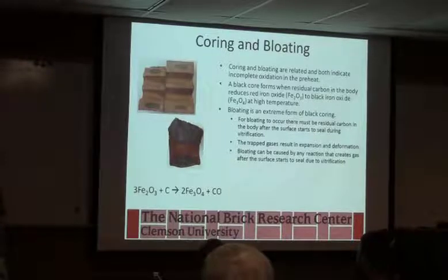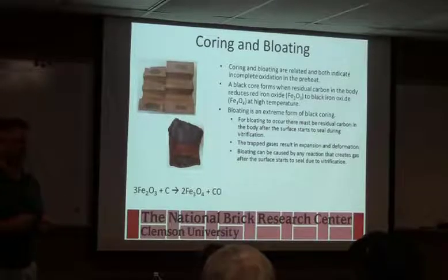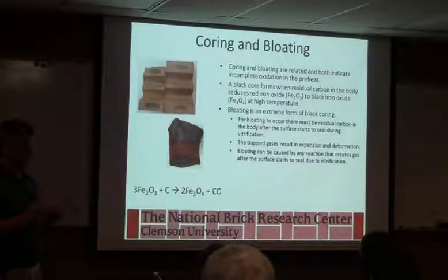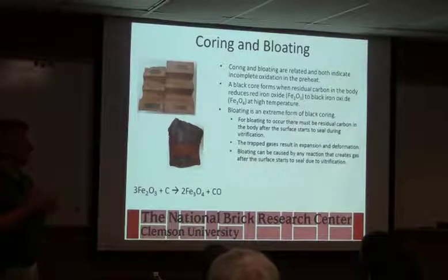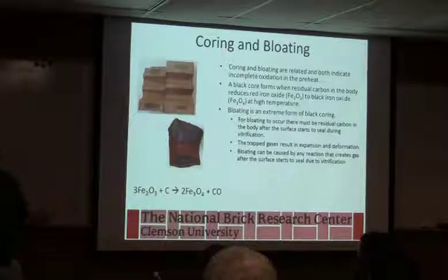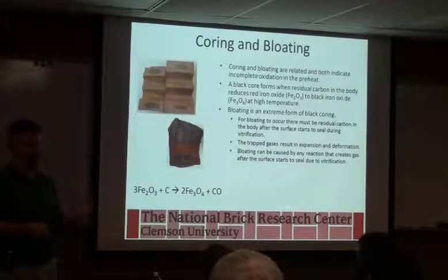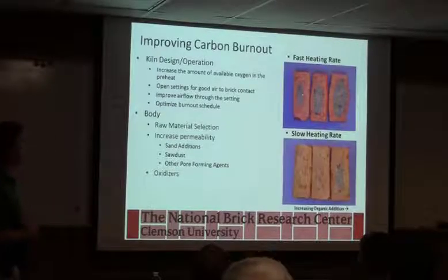So the whole idea is you're trying to produce a firing schedule that gives time for everything to happen. You've got to get the water out. You've got to get the organics out. You've got to get the thing to densify. You've got to get the pore structure. You want to keep the differential shrinkage to a minimum that isn't going to put stress and cause cracks in your brick. So everything that you're doing right now, you're actually doing a lot to get that brick out to be the right color, the right porosity, the right mechanical behavior. And if things start to wander, this is some of how it presents itself.